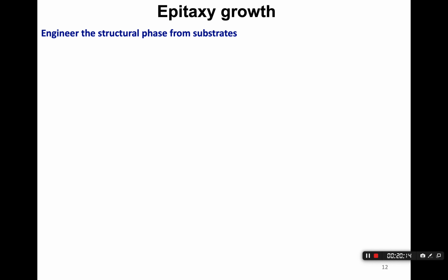So in the end, I'd also like to talk about epitaxial growth. This is a huge topic in the field of thin films. I believe a lot of people are working in thin films, like multiferroic thin films. This is a very hot topic in the field of oxides, especially transition metal oxides. And if you're working on 2D materials, you're likely to grow different thin films and nanofilms using chemical vapor deposition, physical vapor deposition, or molecular beam epitaxy. So epitaxial growth is a well-explored experimental synthesis approach, right?